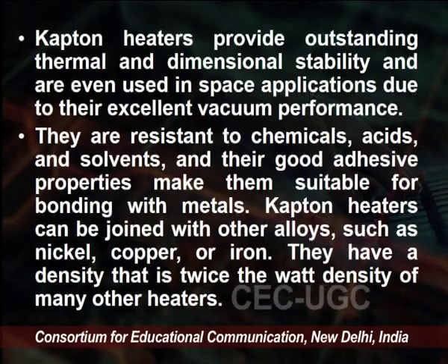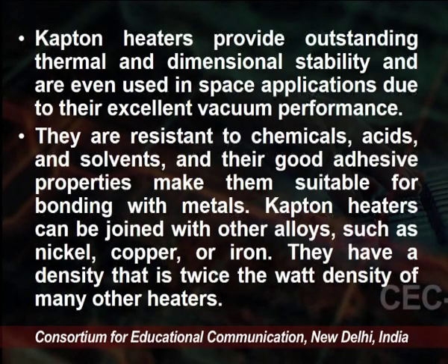These heaters provide outstanding thermal and dimensional stability and are even used in space applications due to their excellent vacuum performance, and they are resistant to chemical acids and solvents. Their good adhesive properties make them suitable for bonding with metals. So, Kapton heaters can be joined with other alloys such as nickel, copper, iron, and they have a density that is twice the watt density of many other heaters.